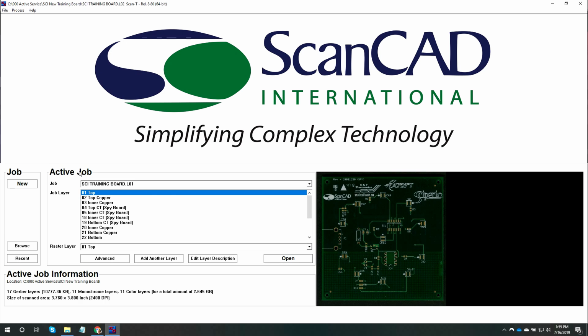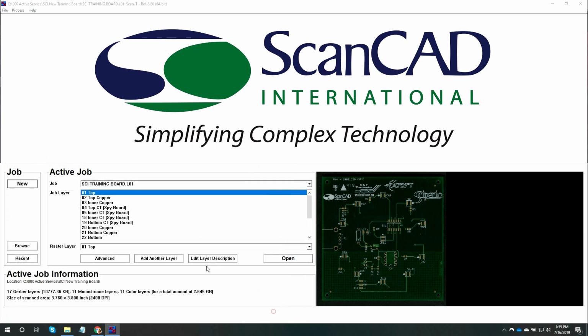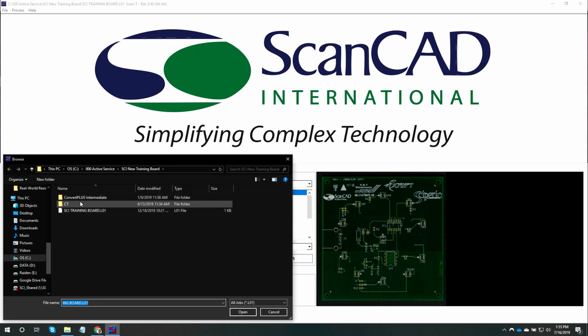This area is broken up into four major parts. We have the job part, which allows us to create a new job, and that can be anything from scanning an image, importing Gerber, or doing any combination of those based on your system configuration. This job area also allows you to browse the directory in which your ScanCAD software is loaded. So for instance, right now we've loaded a project in this directory, and all of the projects in this directory will be visible in my active job area.